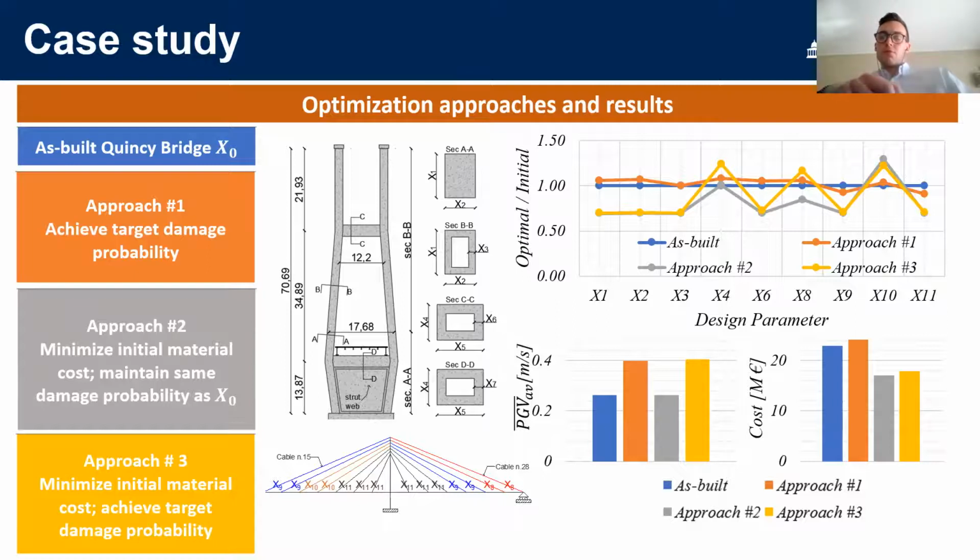Another possible solution would be, for example, the spectral acceleration in the decaying part of the response spectrum, or other parameters that are more correlated with the peak responses of cable-stayed bridges with respect to peak ground acceleration.